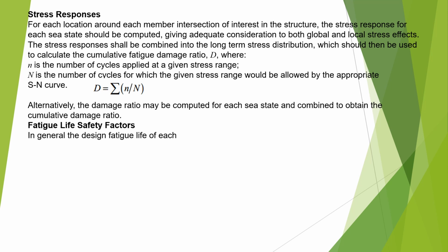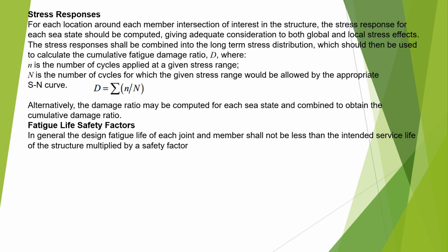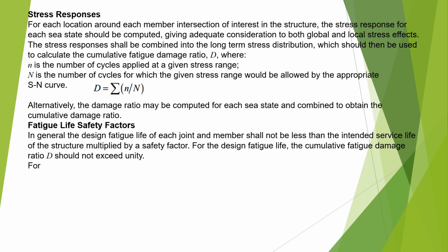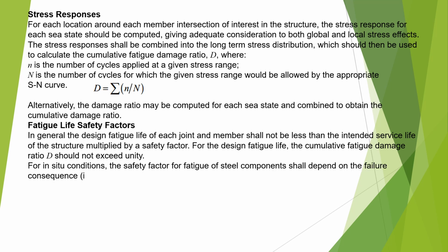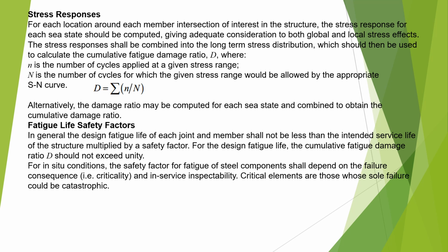And fatigue life safety factors in general. The design fatigue life of each joint and member shall not be less than the intended service life of the structure multiplied by the safety factor. For the design fatigue life, the cumulative fatigue damage D should not exceed unity. For in-service conditions, the safety factor for fatigue of steel components shall depend on the failure consequence. That depends on the criticality and in-service inspectability.